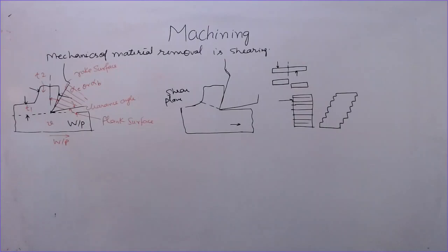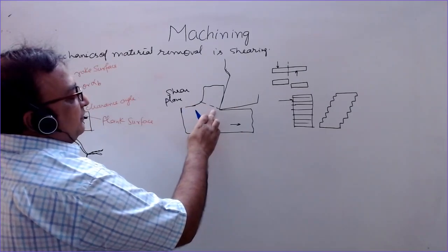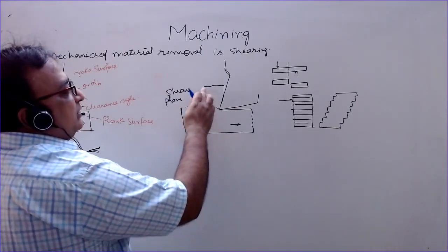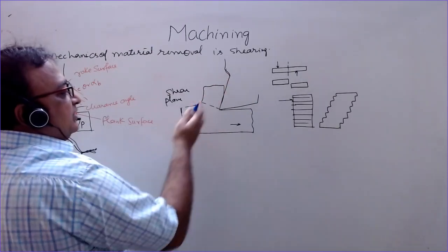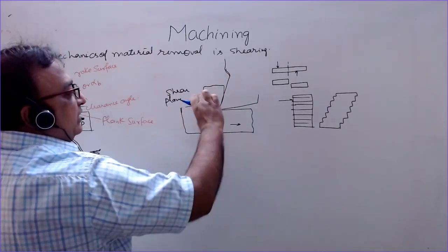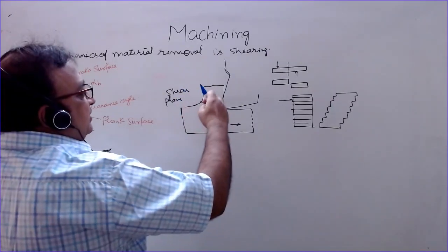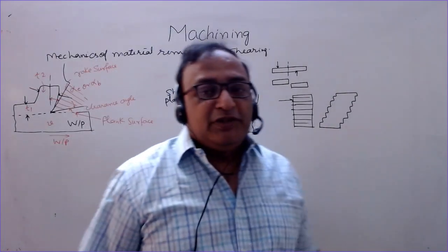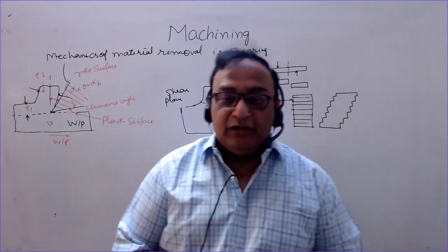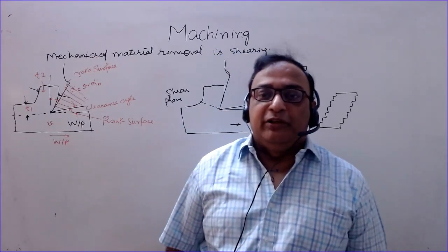So the shearing occurs along a plane, but actually this is ideal case. The shearing occurs here, shear failure along this plane, and this lump of mass is free and it is moving along this. Then the next comes in, this is the depth we have provided for cutting. Then the next comes in and that is sheared here and it moves. So the chips which are produced here, we will be studying after this how many types of chips are produced. Chip is the material being removed.